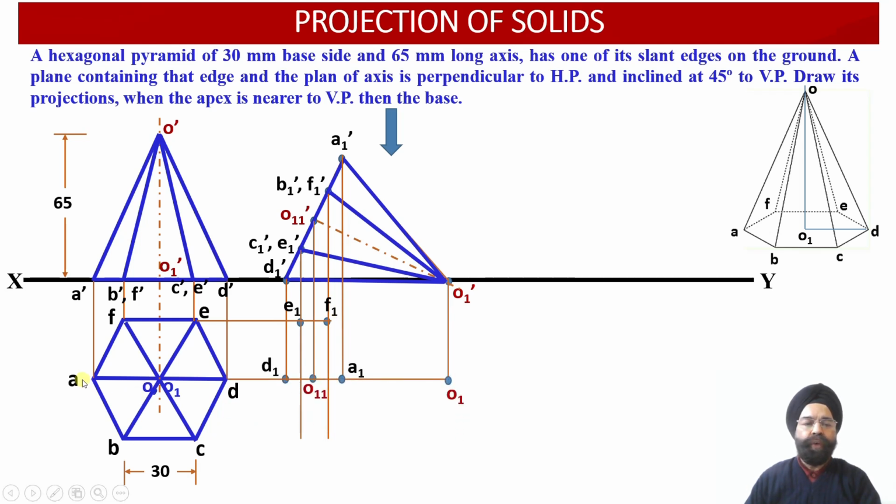projection view. Then over here we have got 4 points which are falling into the same horizontal line: A, D, O and O1. So through these 4 points, again we have drawn a horizontal projector line. Wherever this horizontal projector line emerging from these 4 points A, D, O and O1 is going to intersect with the vertical projector lines drawn through D1 dash, A1 dash, O11 dash and O1 dash, these 4 points we will be able to obtain.